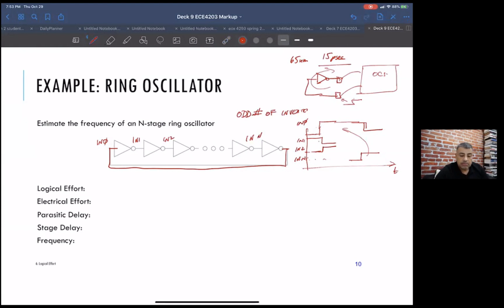It's the equivalent of something like 66 gigahertz. It's very hard to measure that with your probes, even the most advanced scopes or probes, because you've got all sorts of capacitance lying around. So you're not going to accurately measure a delay of 15 picoseconds. It'll be very, very hard to do, okay?